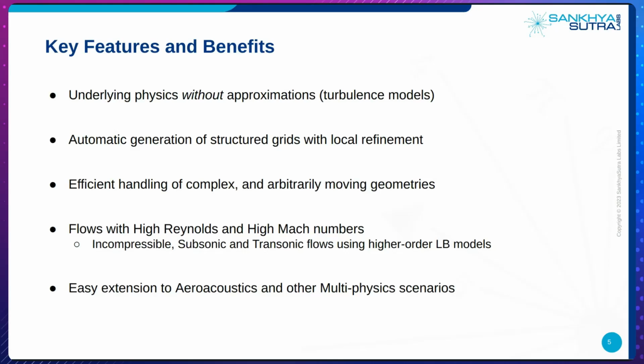We also offer automatic generation of structured grids with local refinement that can be specified by the user according to their needs and desires. The user can either specify spatial regions where they want specific locations in their domain to be resolved with specific resolutions, or they can designate a particular resolution for a surface of their interest in the geometry that they make use of for the simulation.